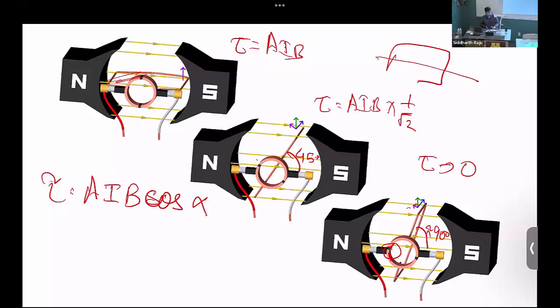We just need to make sure that when we short, the EMF in the loop that's being generated is very close to 0. If the EMF in the loop of the coil is very close to 0, then shorting it is okay because you can short a 0 voltage and nothing is going to happen. If the voltage gets too large and you try to short it, that becomes a problem. So the point at which we short must be such that when the winding is at 90 degree, which is when the commutator segments get shorted, we need to mathematically ensure that the EMF across the loop will be very close to 0. Mathematically, we'll prove that it is 0 at 90 degree, but we need to somehow ensure that too.